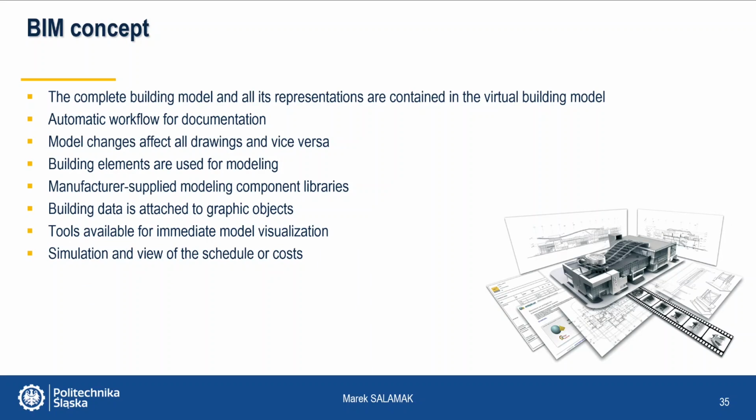The virtual building model contains the complete building model and all its representations. Documentation progress automatically flows between model elements. Model changes affect all drawings and vice versa. Building elements from the component library provided by manufacturers are used for modeling. Non-graphic data is attached to graphic objects. BIM modeling software has tools for immediate model visualizations. It is also possible to simulate and view the schedule or costs.